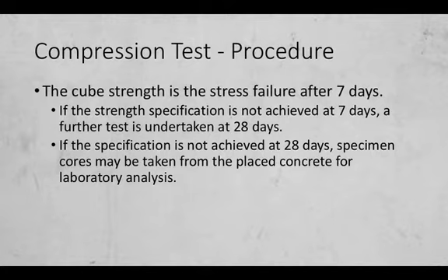So what this means is that at 7 days, after you make the cube soak in the water for 7 days, you test the strength by putting it in the machine that applies the load to apply the pressure. And the strength of the cube would be determined from that.